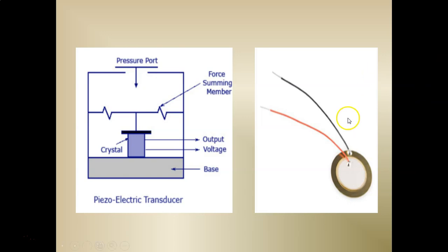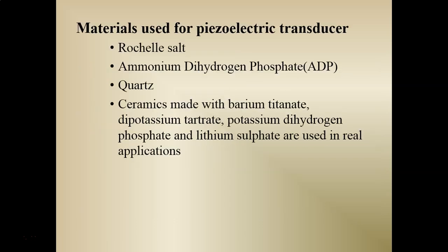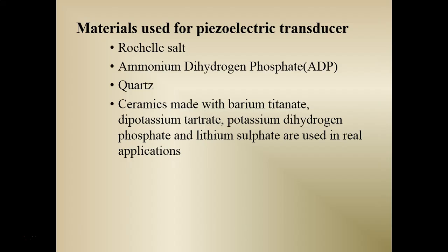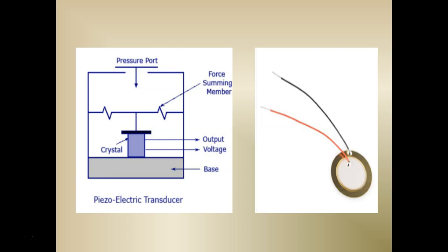On the right side we see a practical piezoelectric transducer. Here the crystal is placed between the solid base and the force summing member. An externally applied force entering the transducer through its pressure port applies pressure to the top of the crystal. This produces an EMF across the crystal proportional to the magnitude of the applied pressure.